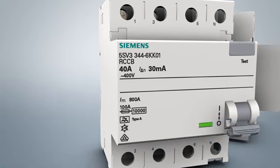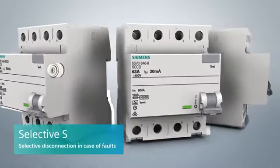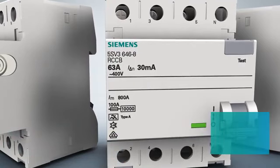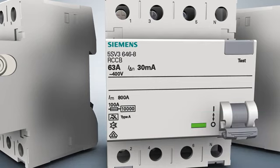Selective residual current protective devices are employed for ensuring selective disconnection of series-connected residual current protective devices in case of faults. These devices have to feature a graded design both with regard to the rated differential current as well as in terms of the tripping time. Furthermore, selective residual current protective devices offer a very high impulse withstand strength of 5 kA.